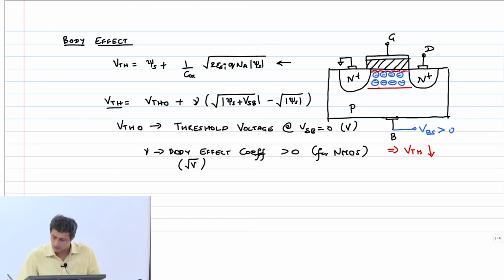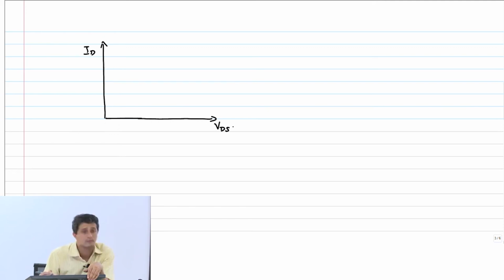So with that, what we have derived is the threshold voltage equation and the on current equation for different regimes, linear, saturation and all that, for a long channel transistor. So before we proceed to the short channel transistor, let me quickly look at what the ID versus VGS will look like. I am going to look at ID versus VDS for different VGS values.